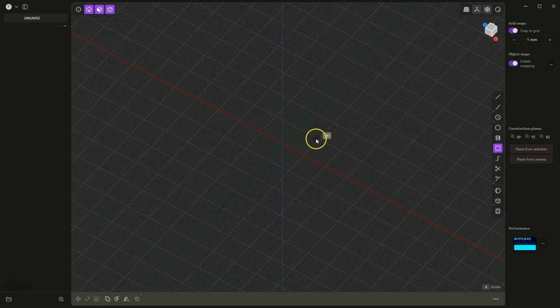Now, I will start drawing the rectangle at the coordinate system origin and pay attention to what the dimensions of the rectangle will be. These dimensions of the rectangle change in even millimeters because I have Snap to Grid enabled. So, in this way, I can specify the exact dimensions of the rectangle. This is not the only way to specify exact dimensions for geometry, but if we want to quickly create a shape that has roughly specific dimensions, this Snap to Grid feature can make things a bit easier.